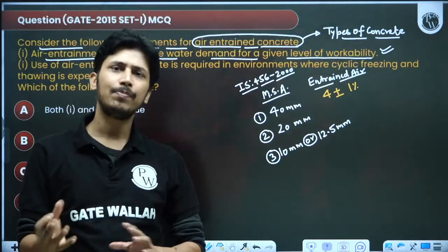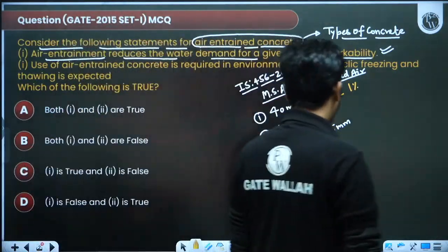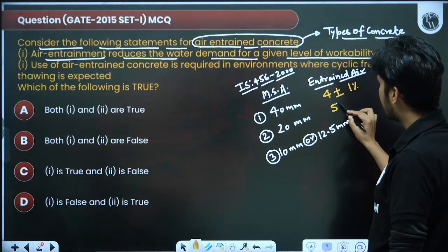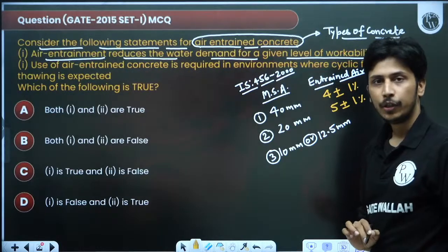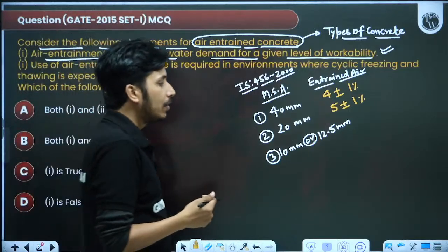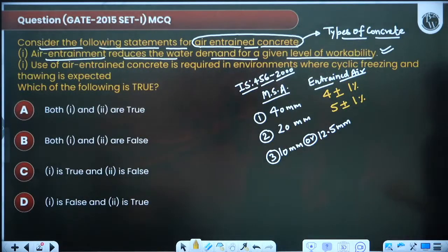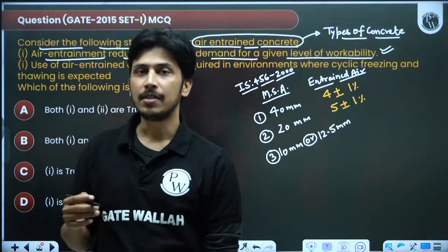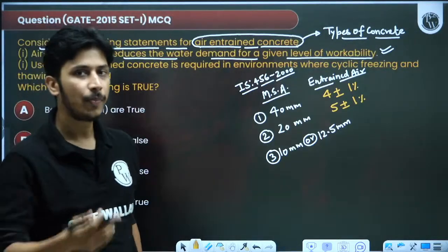You can increase plus 1, you can decrease plus 1. Okay, next. 20 mm aggregates require 5% plus minus 1%. You can use 5% or you can get 6% also. You can reduce by 1% also. So 5% plus minus 1%. Sir, on which page? Some of the students will tell, like Mr. Purohit has told on page 18.